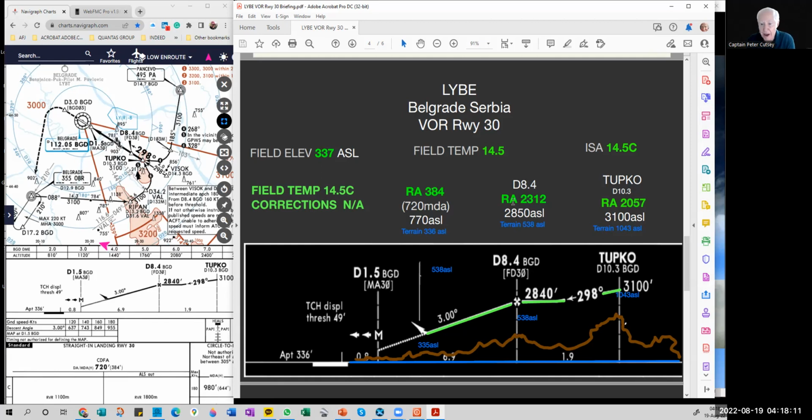Okay. By the final fix, which is the most important last part of your flight next to the landing, because it's your last chance to do a lot of neat things. Your last chance. You've got to check the charted altitude, barometric altitude, and make sure that the radio altimeter reading is what it should be when going by. If it isn't, you'd better go around.